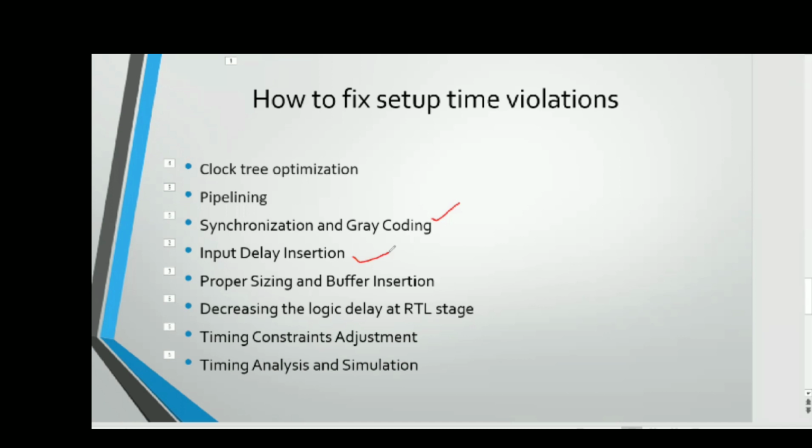Then you have timing errors, where what timing you are expecting and what you are getting are different, with different kinds of violations like setup violations and hold time violations. So there is a timing failure in your design. Then metastability. It leads to your output going to an unpredictable state. So again, we have these consequences of setup time violation. Now, how to fix this?